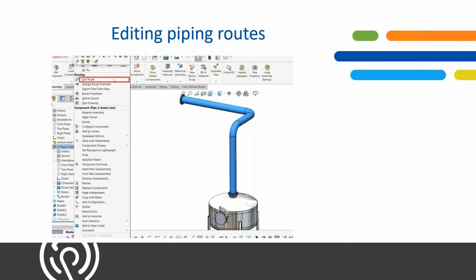With this particular tank that we're looking at here, on top of that tank, we have a slip-on flange, and then we have another slip-on flange. And our routing assembly is going to be what's highlighted in blue. So when that route is activated, we can establish a 3D sketch that can control that, and we can also establish our dimensions that can control that route as well.